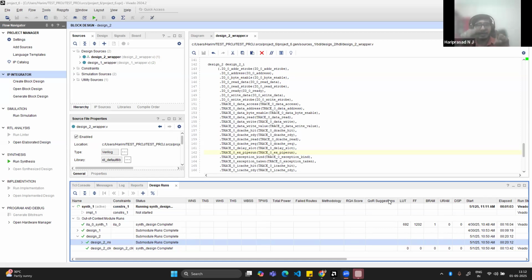Each lookup table, even each D flip-flop, has a mux, and for the mux there is also one memory bit. So for each thing there is a sequence, like the serial vector format SVF file. If you remember, in older FPGAs we used to generate an SVF file. That vector file is programmed in a particular sequence, and that is how it goes and sits.